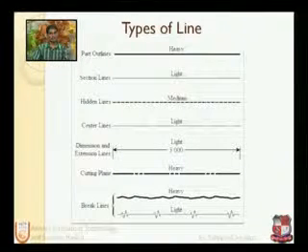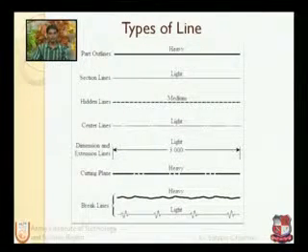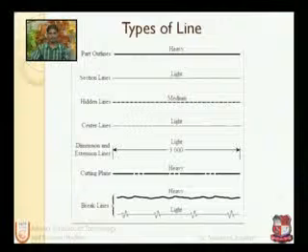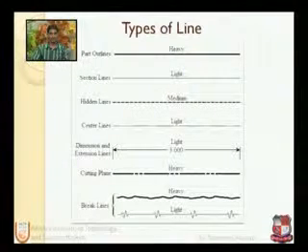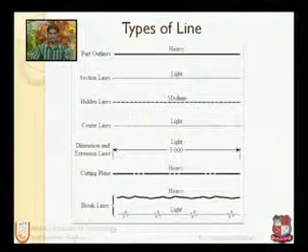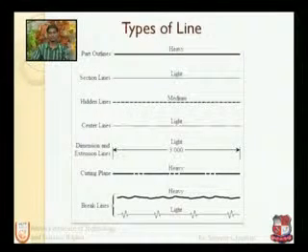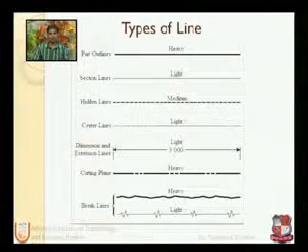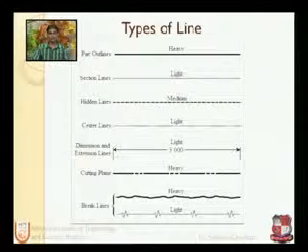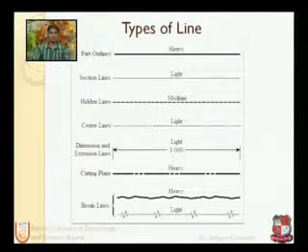Cutting plane line can be shown by a heavy chain, but double dashed chain line. Break lines can be heavy but curvy lines. Break line can be shown by an irregular continuous line or dashed line, as we can see on the screen, and that is drawn as light.